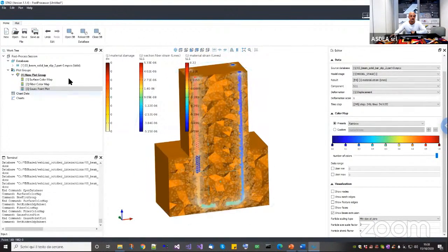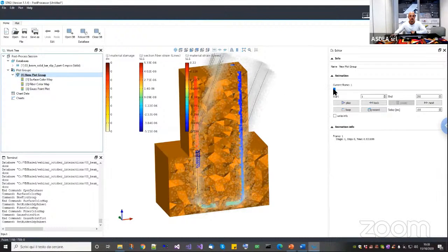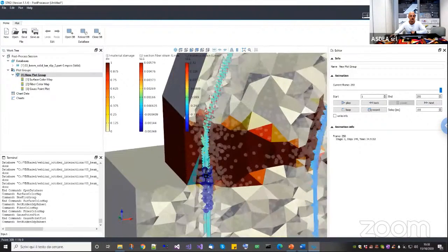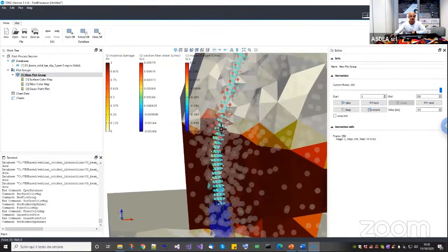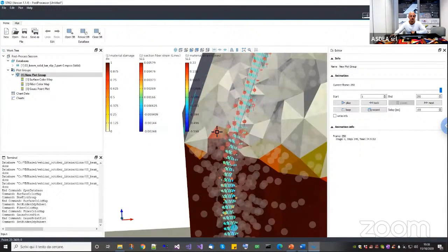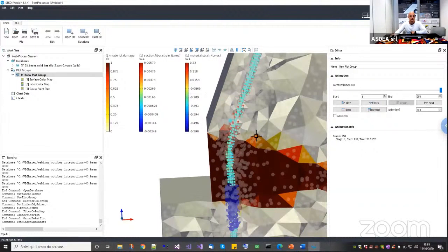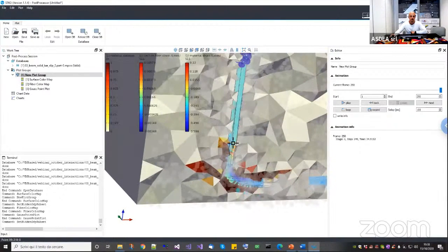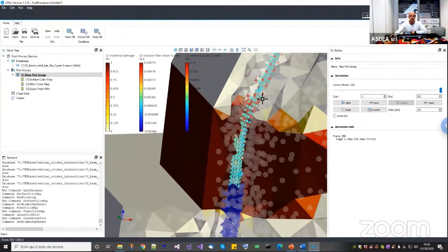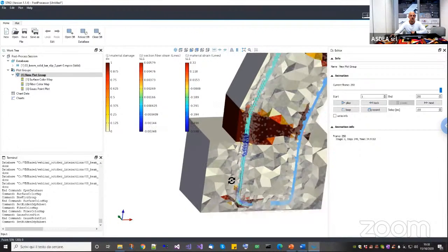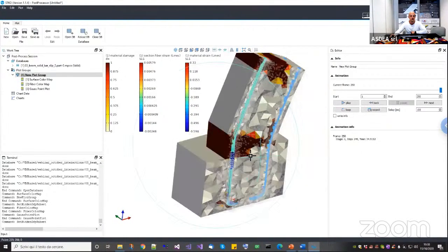Okay. So basically now, let me go back to the, also here in the same deformation. Then let me go back to the end, and finally I will do an animation. But I want to show you how you can see the results of them. As you can see now, here I see a lot of Gauss plots, and those blue and red are actually showing the maximum deformation in these zero lengths, which is the maximum slip. And as you can see, it is concentrated around basically the cracks here, then it goes almost to 0 inside, and then also here, which is basically where the majority of slip is, of course.